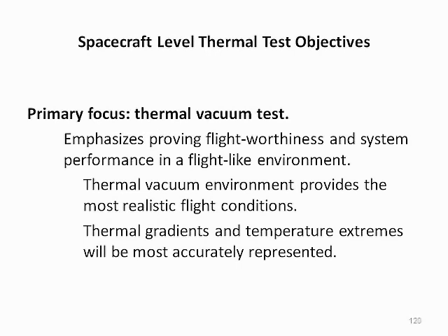At the spacecraft acceptance level, the primary focus is on thermal vacuum tests, which emphasize proving the flight worthiness and system performance of the vehicle in a flight-like environment at the system level. The vacuum environment provides the most realistic flight conditions in which to verify functional performance. Thermal gradients, temperature extremes, and hot and cold spots are most accurately captured at the spacecraft level in a simulated space environment.